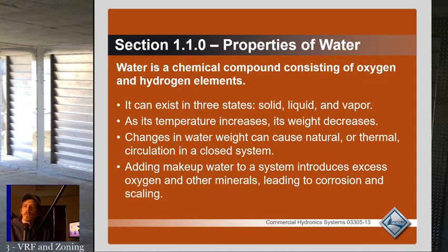All right, adding makeup water to a system introduces excess oxygen and other minerals, leading to corrosion and scaling. Again, minimizing how much water you introduce into a closed loop will exponentially increase the life of that system. So you want to have good, tight systems with very little leaks.